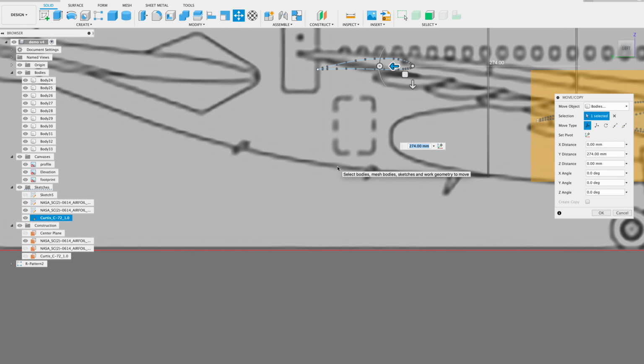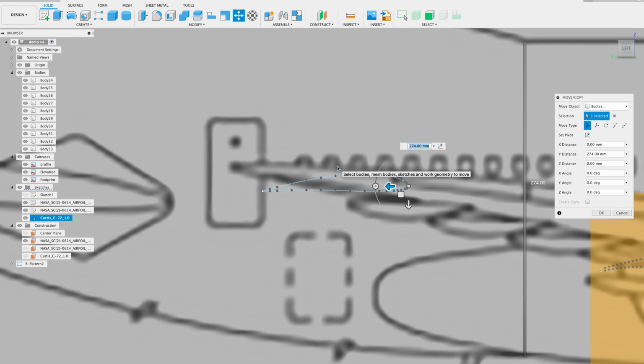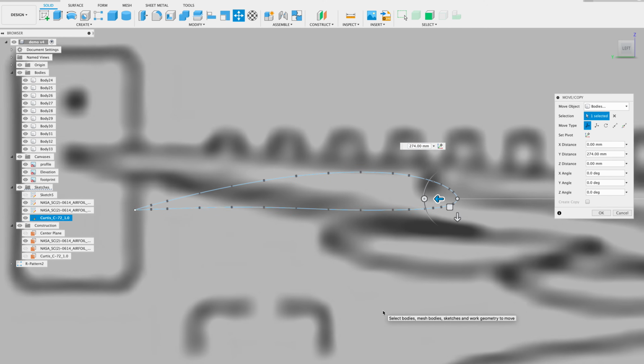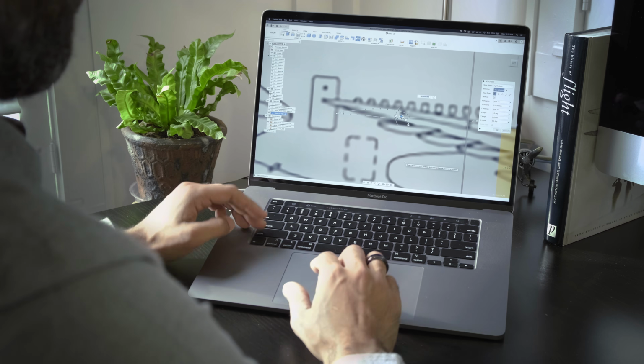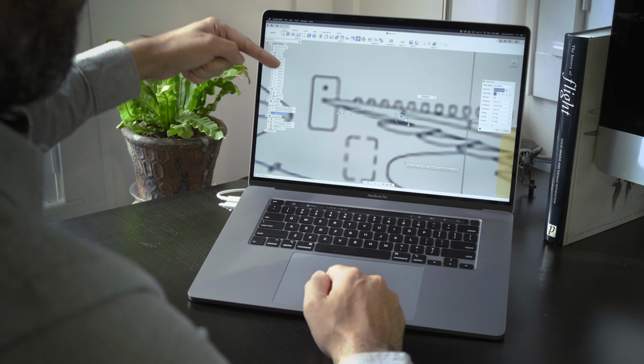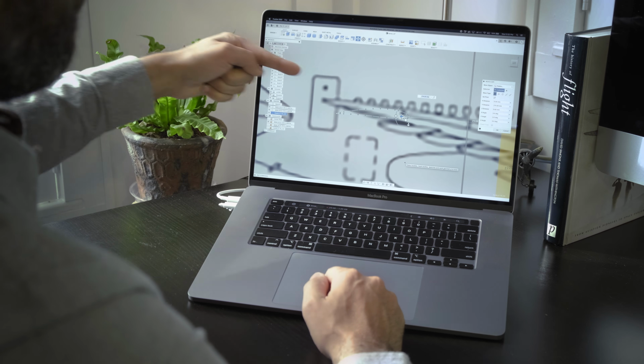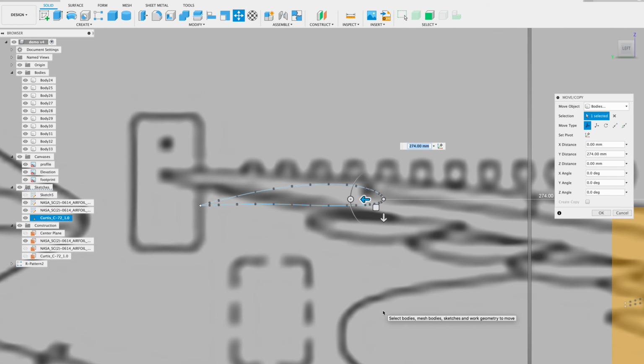Okay, now let's talk washout. As you can see, this plane, the wingtip is actually pointing downwards, and that is known as washout. Okay, so I introduced a new concept to some of you called wing washout. To others, this is a very familiar thing, but I'm going to give you a quick overview of what it is and why you need to have this, or why you should have this at least, in your wing design.